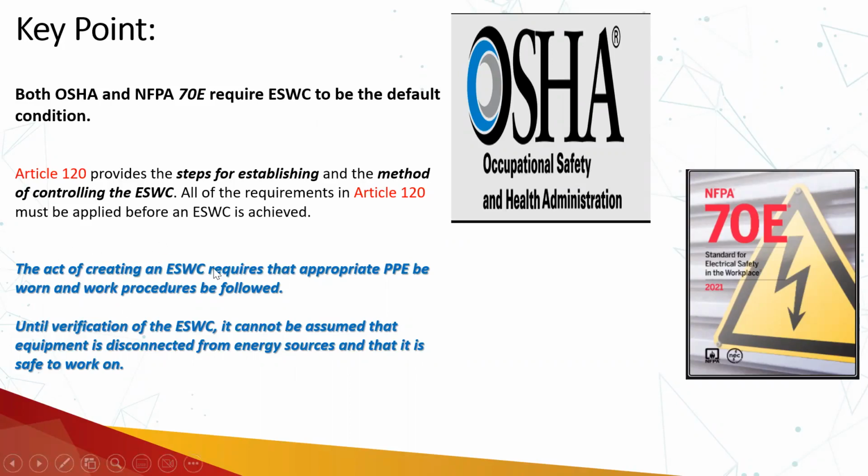The main step of the electrically safe work condition is verification. Until the verification is done, it cannot be assumed that the equipment is safe to work on.